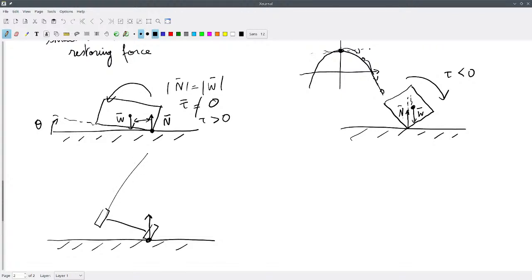And if somewhere on this truck there's a center of mass, let's say the center of mass is here. Under this particular tilt angle, as long as the weight is applying to the left of the normal force, or to the left of the contact point for the truck between the two tires, then there will be a torque that brings the truck back to its stable equilibrium, which is the two wheels on the ground.